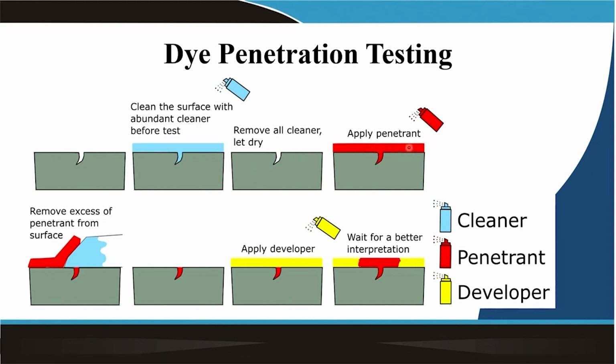After the penetrant is applied, you have to remove the excess penetrant from the surface by cleaning it with water or alcohol. As soon as you remove it, naturally some penetrant will remain deep inside the surface, where porosities or defects are there. After that you apply the developer. Developer is usually a white powder, sprinkled on the surface, or a white powder dispersed in solution.